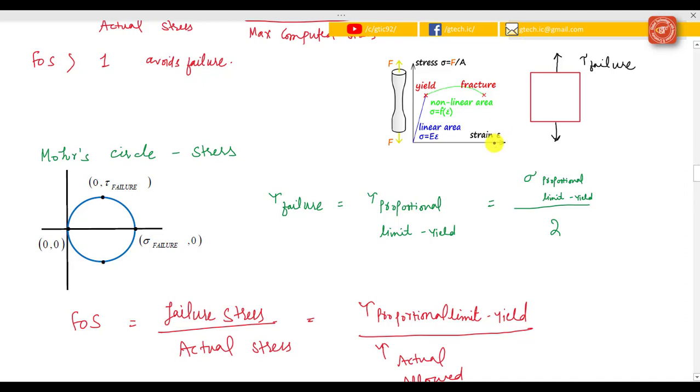So here is our simple tension test, and here is our failure, and we pull on it with uniaxial load, but now we will draw a Mohr circle, and we can see from different planes at the stress plot, at different orientations, we can also experience the shear stress.